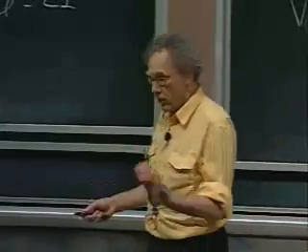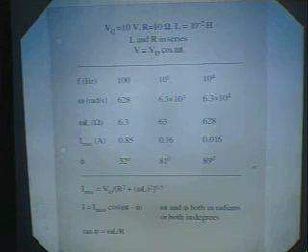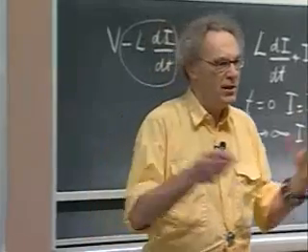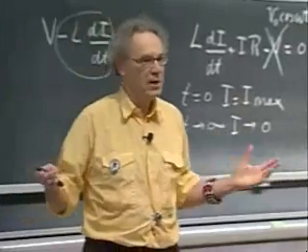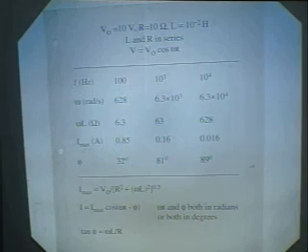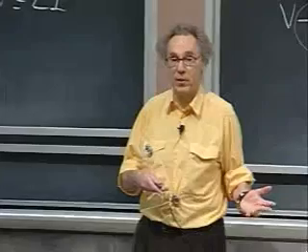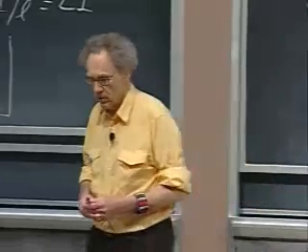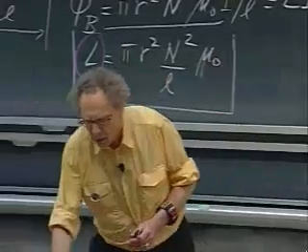And then I will turn on, all of a sudden, the 10 millihenry. So first I will make you listen to music whereby there is no 10 millihenry in there. And then I will turn on the 10 millihenry, and what you will hear is that the violins disappear. Because the current reduction is now huge on the high frequency, but is very little on the low frequency. And that's the idea of what a self-inductor can do for you. So if you listen to this,